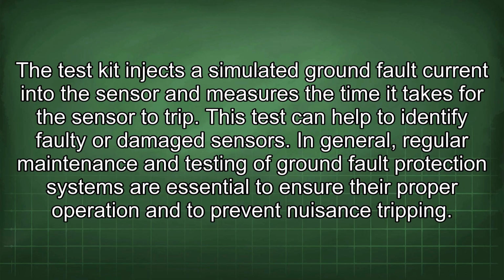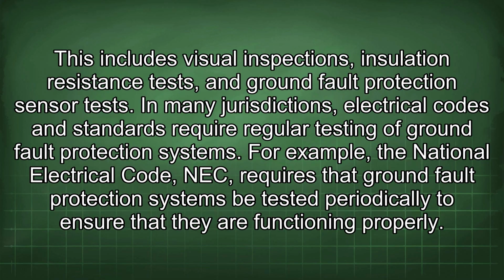In general, regular maintenance and testing of ground fault protection systems are essential to ensure their proper operation and to prevent nuisance tripping. This includes visual inspections, insulation resistance tests, and ground fault protection sensor tests.